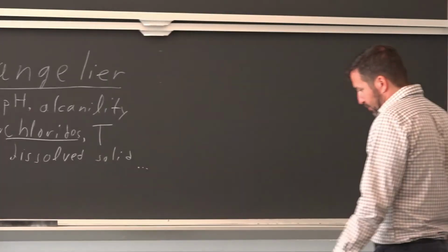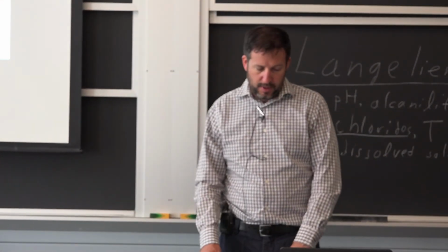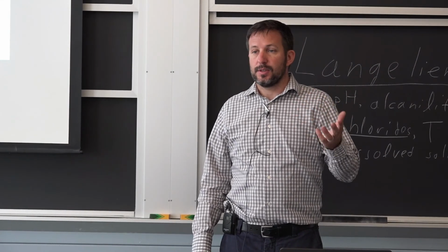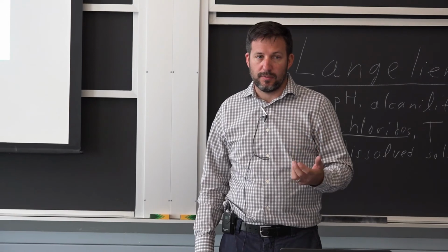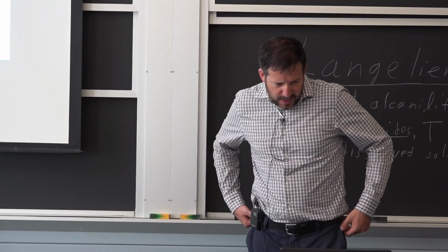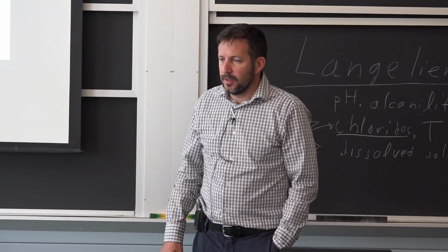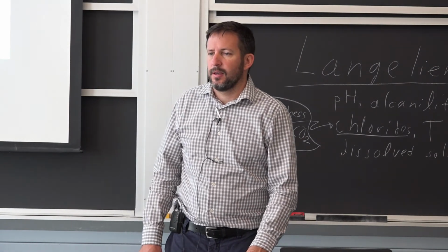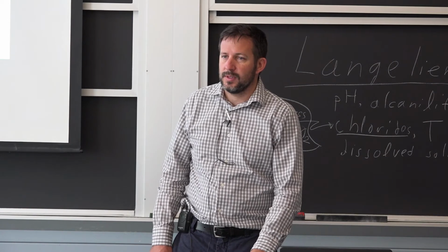Okay, so stainless. It means that it has the natural protective layer, but the moment you break that layer, now all of a sudden you start having pitting. It's going to have that bleeding rust effect. They were not expecting this. They had another project before with stainless steel that succeeded in the same area. This was in the Hamptons in New York, fancy homes.